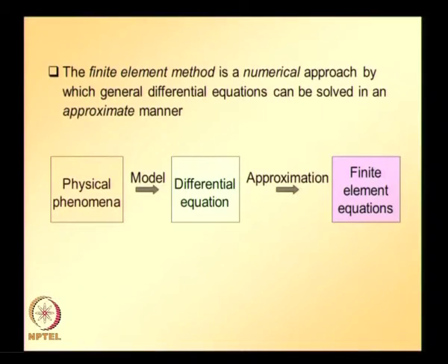So, basically these are the steps that are involved in solving a physical problem. First, the physical phenomena needs to be expressed in a mathematical form as a differential equation which needs to be satisfied over certain domain subjected to some boundary conditions. And this approximate solution of this differential equation we can obtain through finite element method.